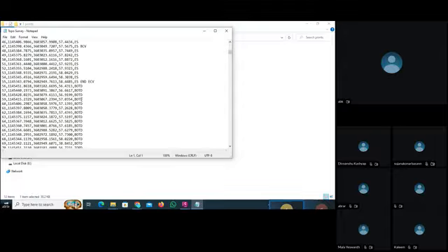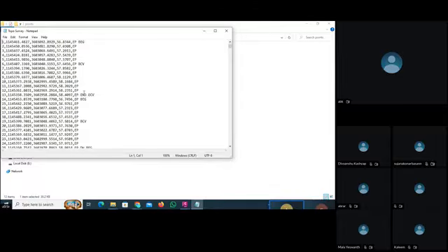For example, if there is a building, you tell your surveyor that whenever you get the building points, you give the description as BLD. When you start that BLD, provide a beginning there, and when you end it, provide an end there, and in the center, provide continuous points. So if your surveyor sets all the points as per your flow, then it will be easy for you to make the linework.